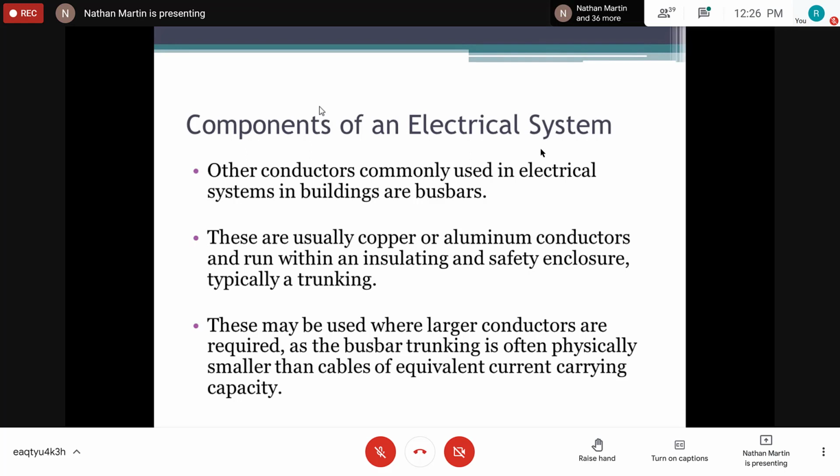No, the thing about the bus bar trunking is that when tightening your cables onto them, you use a lug and not a bolt on board. Now, one thing you need to understand is the torque requirement of these bus bars. Because of the high current we expect it to carry, you have to ensure that these cables are affixed to it properly.